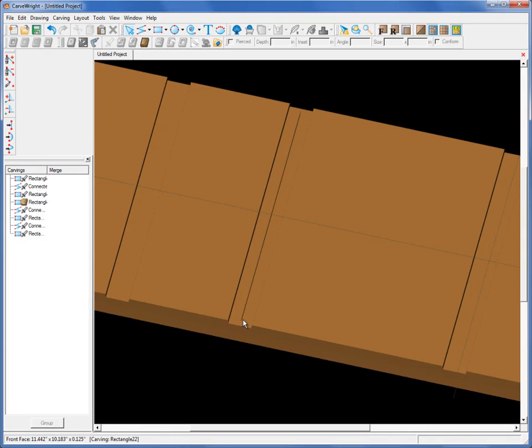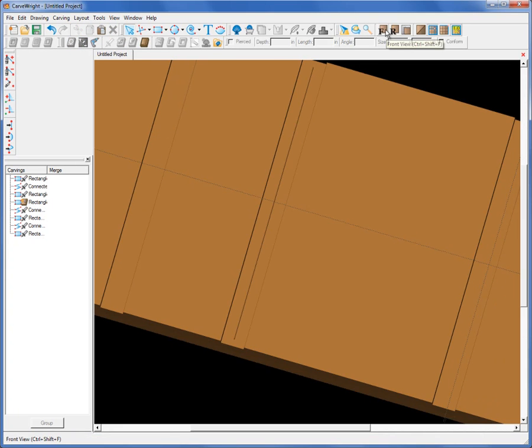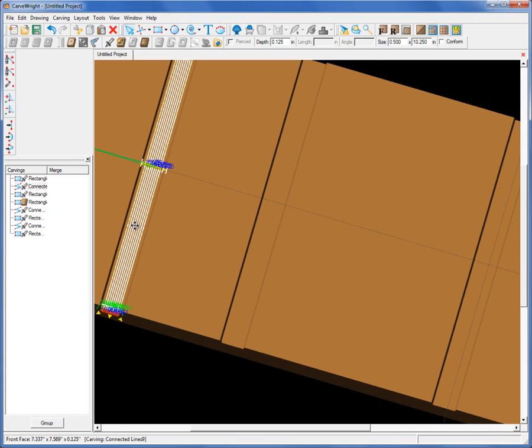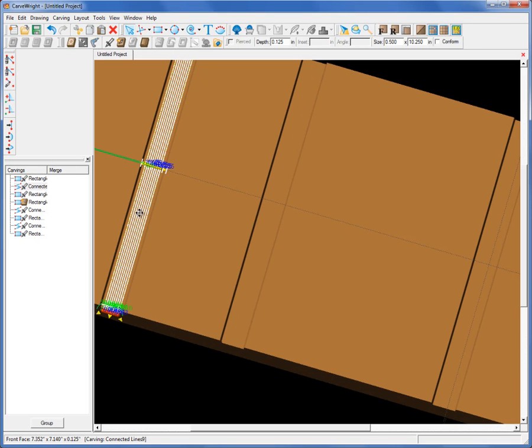If you're really picky, you could always just draw a single line down the middle and assign it the 3/8 inch bit if you want to. So if you do own the 3/8 inch straight bit and you're using it for creating 3/4 inch wide slots, then it wouldn't be necessary to draw all these additional lines in there. This is just showing you how to use the existing cutting bit that comes with the machine.